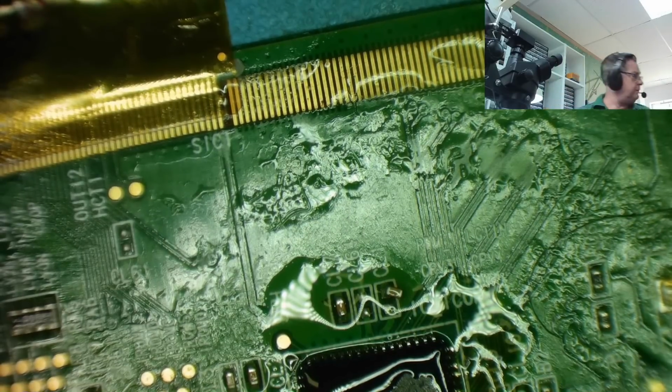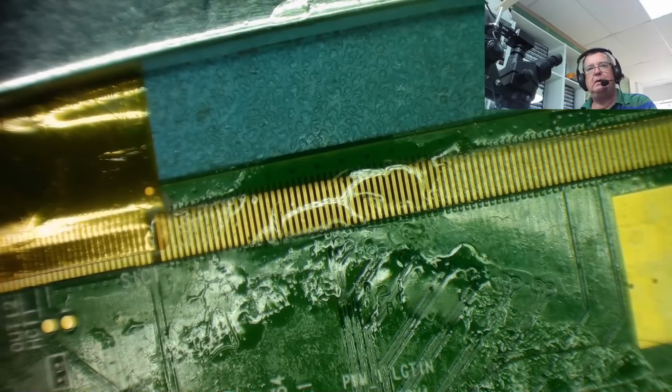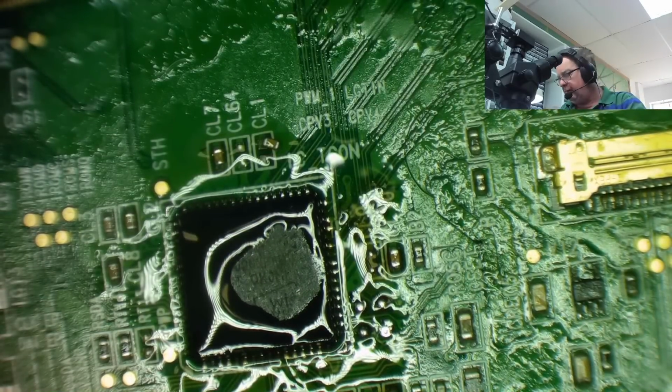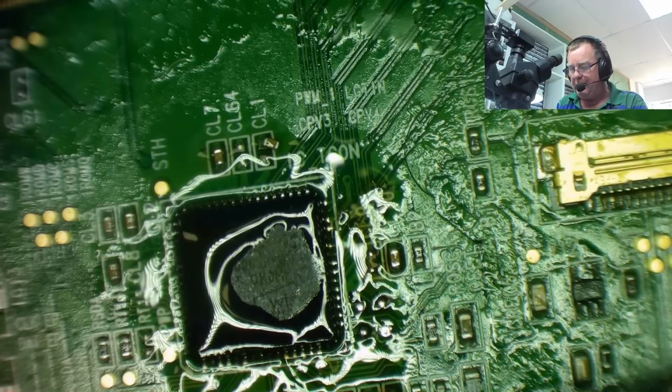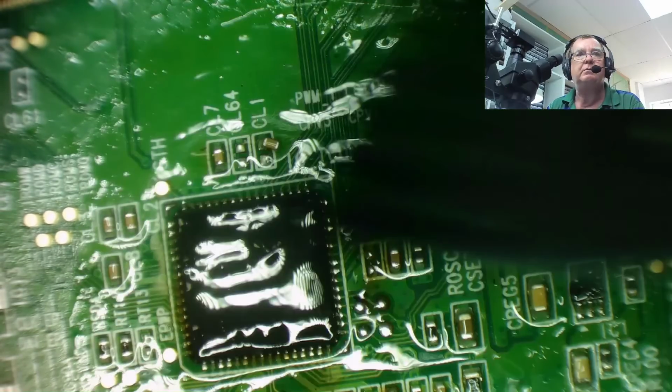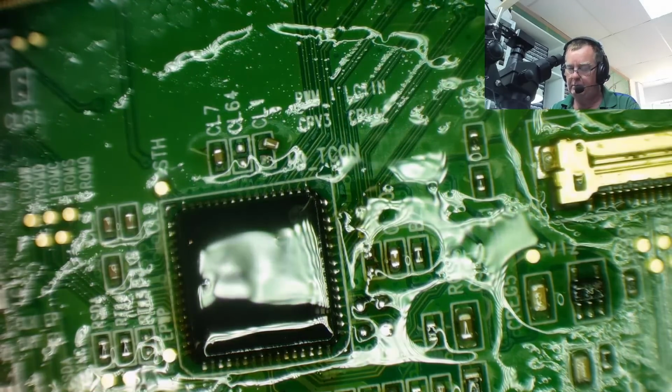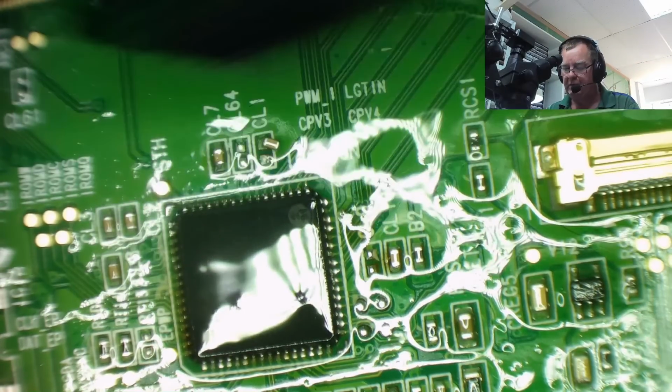Where's my little bit of isopropyl? And let's see if that's looking good. If it's looking good, then we can get the hot air in, reflow it, and it should stick down nicely. And then after that, it's basically just a matter of replacing all the EPROMs and the couple of 3 capacitors that we dislodged. And we should have a good job. If there's any pins that don't look like this soldered, I can always come back along and have another go at them.